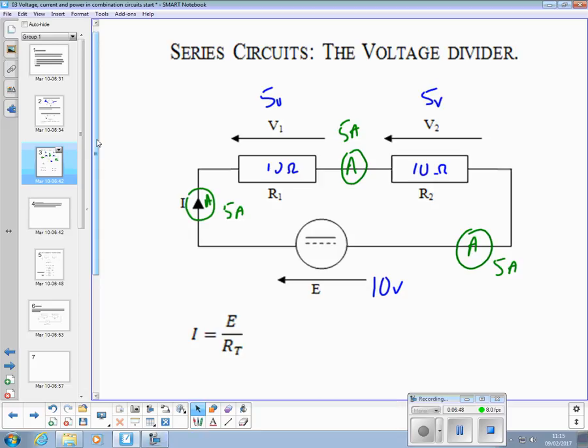The point being made is that a series circuit is a voltage divider. So if we add a third resistor of the same value, we'll divide it up 3 times. And we'll formalise that next week with Kirchhoff's voltage law, that you may remember from the earlier electrical principles module on BTEC if you've done that.